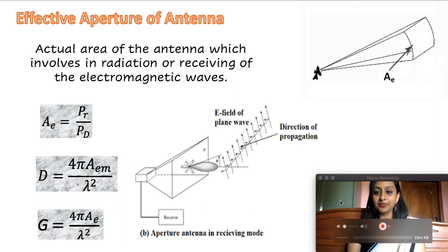Okay, so to summarize what we studied in today's session: we started with the antenna. If I want to design an antenna, what I need to know is the frequency. The second thing is whether I want a directional antenna or an omnidirectional antenna. For an omnidirectional antenna, its radiation is put out in all directions, and directivity and gain would be 1.